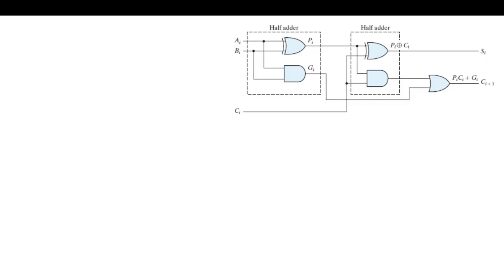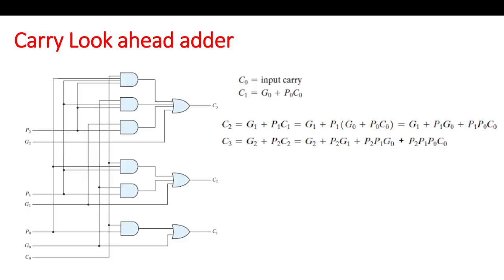So with this, we have seen that this is generated from a header which gives propagate XOR and this generate statement. So now we need a circuit for the next stage carry, generated without depending on the previous stage carry. Now if you have, say, a 4 input AND gate, it can be implemented using n-1 gates. So we need 3 gates.